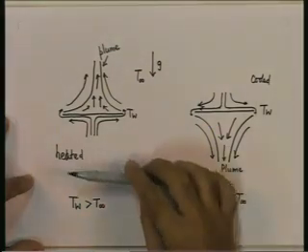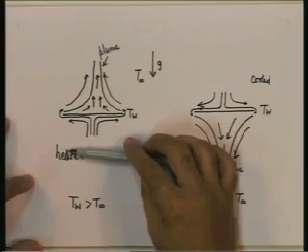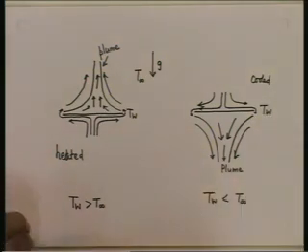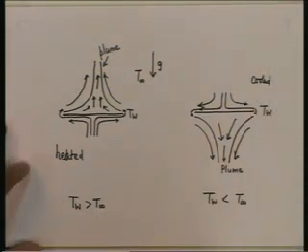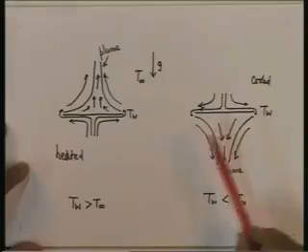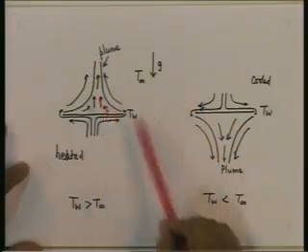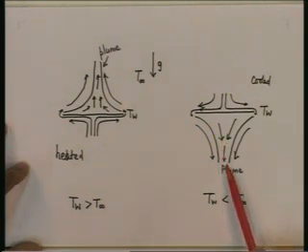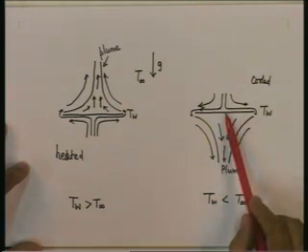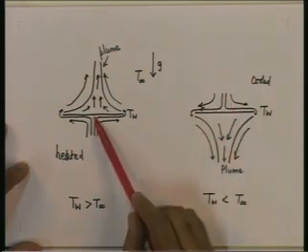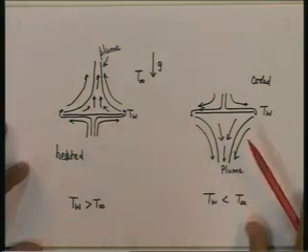In case of a heated surface, the general tendency of fluid surrounding the surface will be for moving up. In case of a cooled surface, the general tendency of the fluid surrounding it will be to move downwards. And because of this, we should appreciate that the situation of a heated surface facing upwards will be similar to that of a cold surface facing downwards.